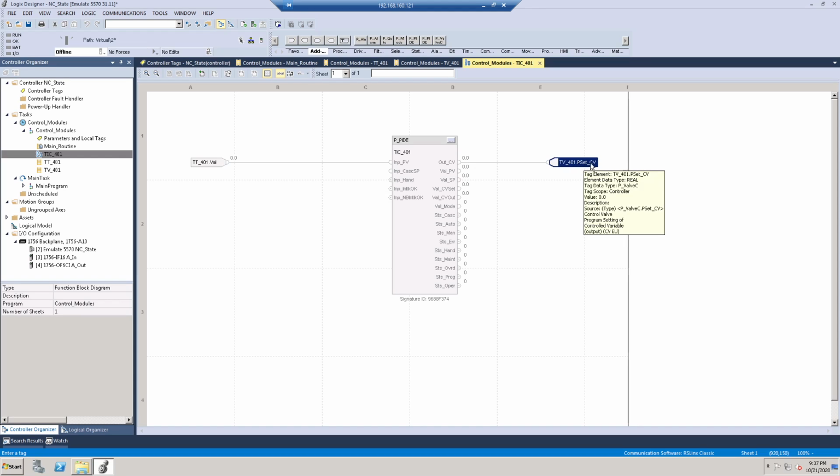So that's what this is sitting here. This is saying P set CB. This is saying if it's in program mode, which it will be once we set up our sim logic. If it's in program mode, which just means that the controller is in control of that valve, because you could have it in operator mode, which is you let even if we tell it to open to 100% from the controller, it's not going to do it. Only the operators can either manually open it or they can send HMI commands to open it.